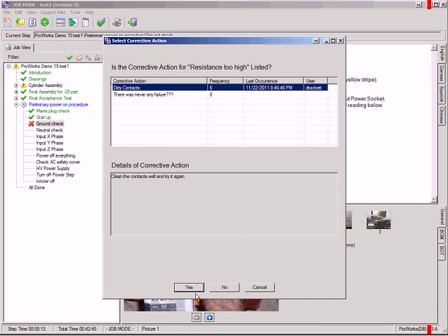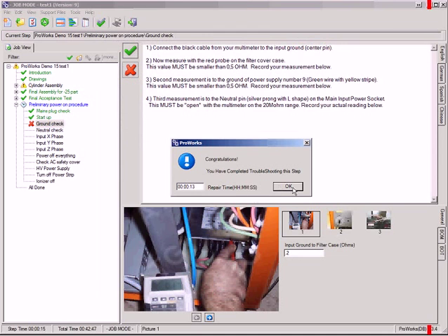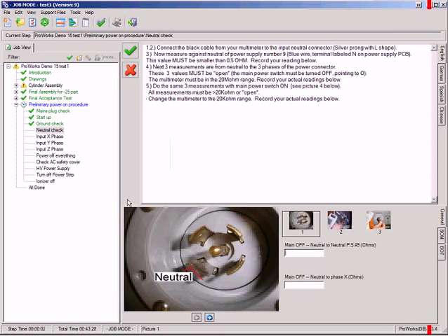And again, keeping track of your time. So you can go through this whole process to make sure that the machine is set up. If you actually have the time to, and you have an RS-232 interface, you can go ahead and make the measurements yourself. We have some people who use multimeters hooked up to a 488 or 232, and they can just read the meters directly rather than making the user type them in. But it just depends upon what level of automation you want to implement.